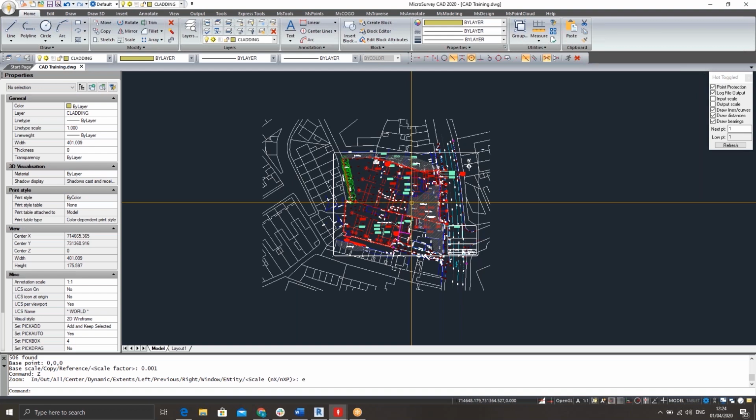We don't want that to happen before we bring our CAD file into our field software, because our field software will try to present a zoom extents upon first import of any reference file. So again, you might get a situation where a user cannot find his information because of the zoom extents, because there's an object at base point or just a drawing object that is left to the side by a designer that they missed. So again, identifying that prior to moving out into the field software is important.